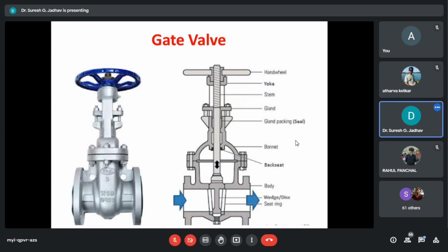Another is pinch valves and butterfly valves. Ball and plug valves can also be used for flow control with say port closing elements. Moreover, the design of quadrant valves are inherently better suited for emission control applications. The linear stem movement of the gate and globe valve tends to open the path of emission release, and in its dynamic mode, emission can be dragged along the stem.